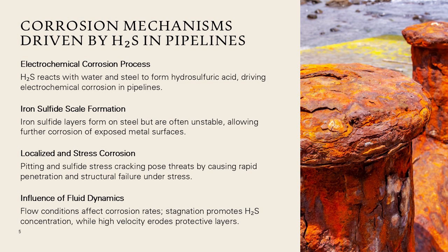Localized corrosion such as pitting is particularly dangerous because it can lead to rapid wall penetration even if average corrosion rates seem low. Under certain conditions, especially high tensile stress and H₂S presence, sulfide stress cracking, SSC, may occur, compromising the structural integrity of the pipeline. Fluid dynamics also influence corrosion.